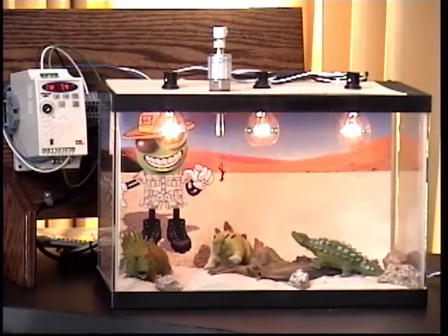And what you're seeing now is the temperature went down, and we actually took a GS1 drive, single-phase input, that has 3-phase outputs. This was a little bit unique, but we took 3 little 40-watt light bulbs that put out some heat. We wired them in a Y circuit because they're 120 volts, and although the drive is a 220 output, by connecting them in Y, we're putting about 220 across, basically two 120-volt bulbs wired in series. We set some parameters on the GS1 drive to keep it in the lower frequency because these bulbs do put out a lot of heat.